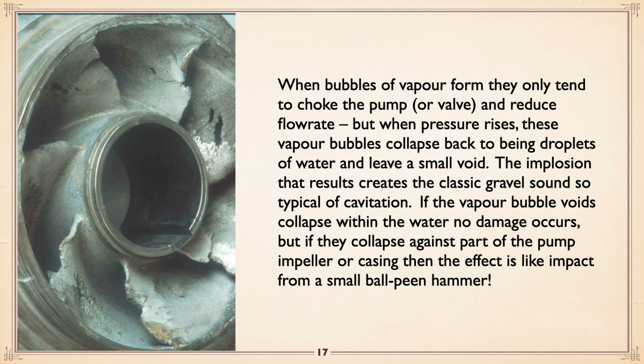cavitation by itself is not a problem if the bubbles reform as the pressure goes up away from anything, right in the liquid itself. In other words, you create a little bubble of vapor, but when the pressure comes back, that little bubble will turn into a much smaller drop of liquid, and the bubble will then collapse. So it gives a very gravelly sound, very much like vortexing, but a real gravelly sound.